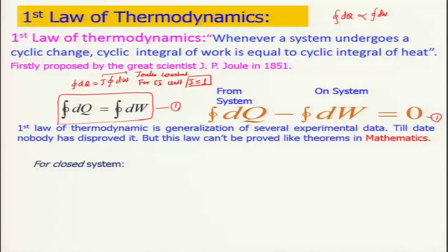but for a lot of systems we will practice with, there is a closed system and there is an open system. A closed system is one where there is interaction. Let us say this is your system, a kind of room where heat is transferred, and there is no work done. This is your system boundary. Therefore, this is known as a closed system. A closed system is one where there is an energy interaction between the system and its surroundings, however, there will not be any mass interaction.